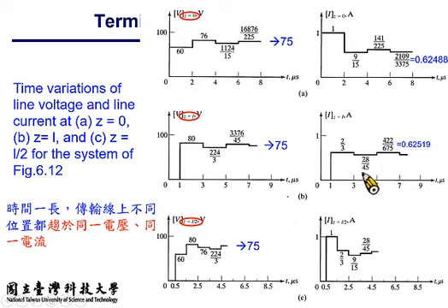The currents will eventually, even though they are quite different at the beginning, as the time progresses, converge to 0.625 amp eventually. So as long as you observe for a sufficiently long time, the currents and voltage will converge to the same value on the transmission line for the case of a DC voltage source.